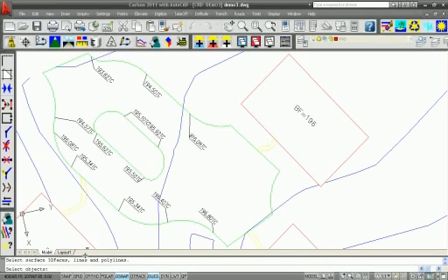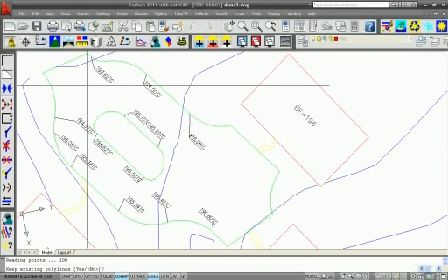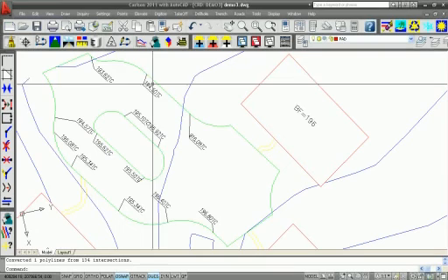And select the 3D faces, lines, or polylines to elevate it by. So I could type in all and select all the contours. I'm just going to click on the 3 that are close by. So I have 3 contour lines selected. I'm going to hit enter. Keep existing polyline? I'm going to say no. And change the layer? No, I don't need to. And it says converted 1 polyline.